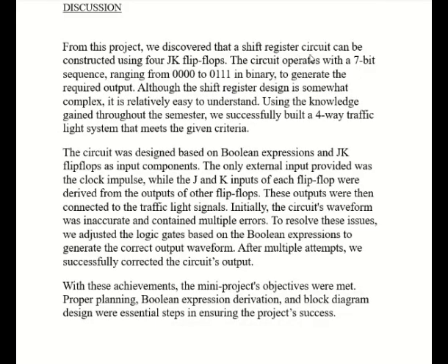We discovered that a shift register circuit can be constructed using 4 JK flip-flops. The circuit operates with a sequence ranging from 0000 to 0111 in binary to generate the required output. Although the shift register design is somewhat complex, it is relatively easy to understand. Using the knowledge gained throughout the semester, we successfully built a four-way traffic light system that meets the given criteria.